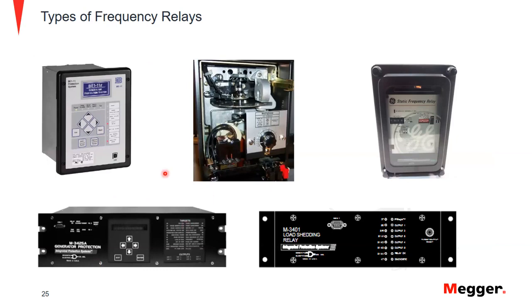So these are a few types of frequency style relays. We can have a little newer microprocessor based, which comes in different shapes and sizes. We have that old CF1 there. I think they're still in service today. I have tested a few of these old guys years ago. And then we also have the old static relay, which is GE, and these guys are still around as well. And even some manufacturers are putting out their own load shedding relay, which is specific for that particular application. So in general, the frequency element can come in all shapes and sizes.